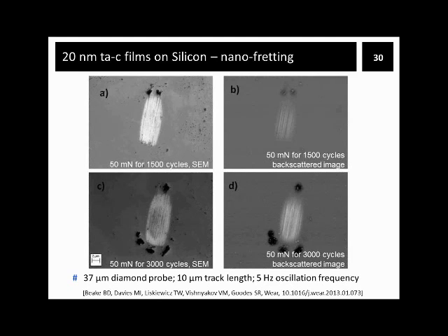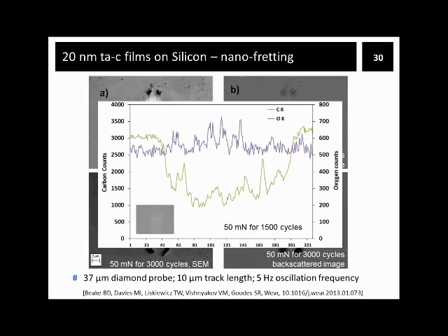So when it comes to fretting, we analyzed surface damage with SEM images, revealing fretting scar and wear debris morphologies. However, more specifically, we were interested in EDX analysis here. And EDX line profiles taken across the fretting wear scar allowed us to measure gradual wearing of the films.